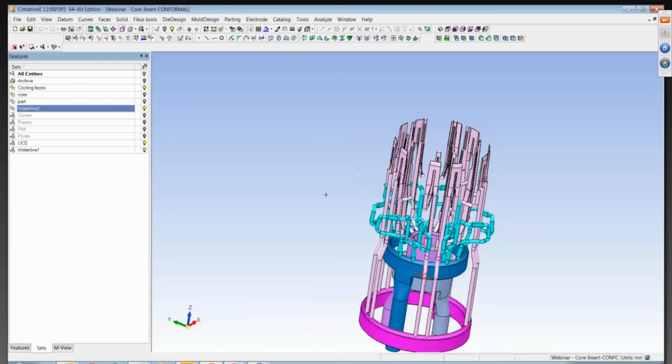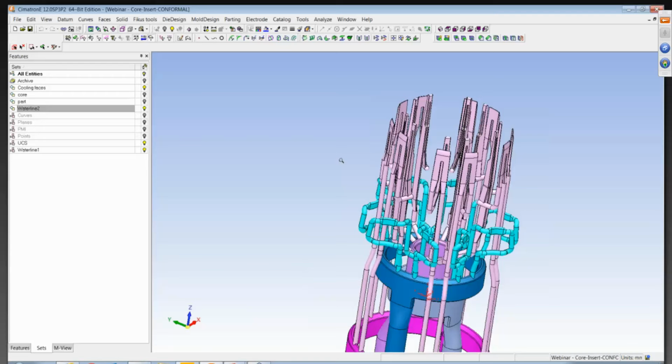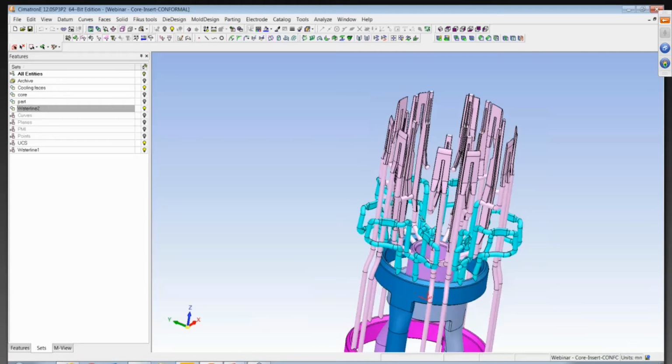Understanding that helps us to see that probably we're going to have to push that water in at a quicker rate in the purple rather than the blue. The idea of uniform, again, we want to get the heat out all at the same time. So that's a factor to consider when we start to see slowdowns or the distance and the total linear distance of the water line being different from circuit to circuit.